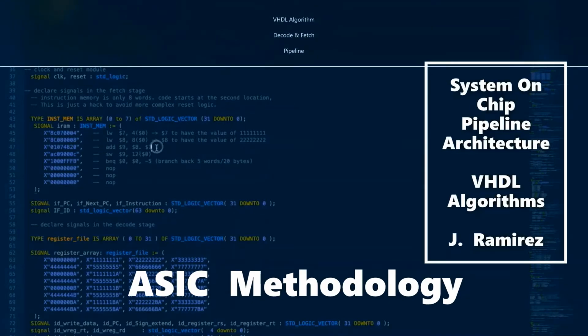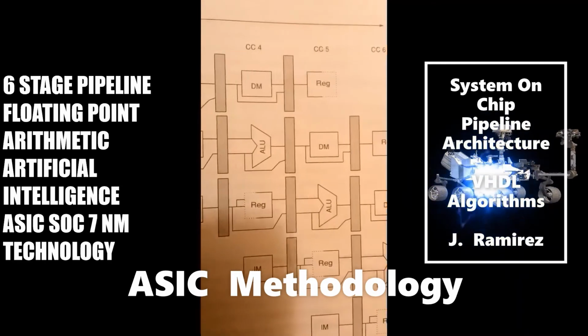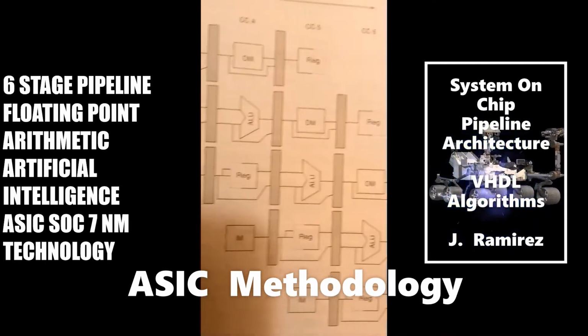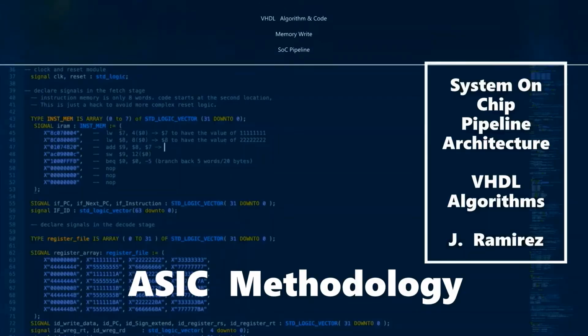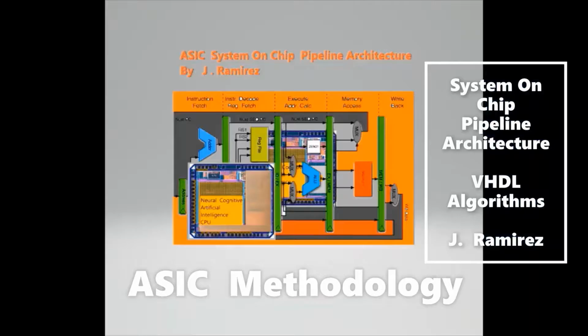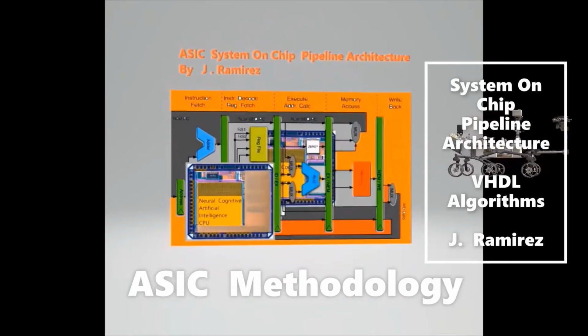The decode stage is the stage of the pipeline where the fetched instruction is decoded and values are fetched from the register bank. It is responsible for mapping the different sections of the instruction into their proper and correct representations. The opcode and function codes are sent to the control unit, and the outputs of these corresponding components are then clocked and stored in the next stage.